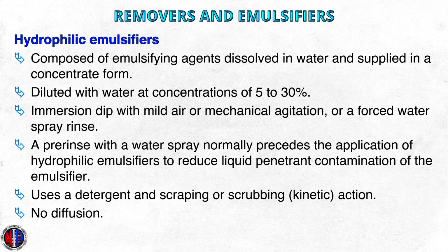Hydrophilic emulsifiers. Hydrophilic emulsifiers, often referred to as removers, are composed of emulsifying agents dissolved in water and are supplied in a concentrate form. They are diluted with water at concentrations of 5 to 30% and used as an immersion dip with mild air or mechanical agitation, or as a forced water spray rinse at dilution ratios of up to a maximum of 5%. A pre-rinse with a water spray normally precedes the application of the hydrophilic emulsifiers to reduce liquid penetrant contamination of the emulsifier.